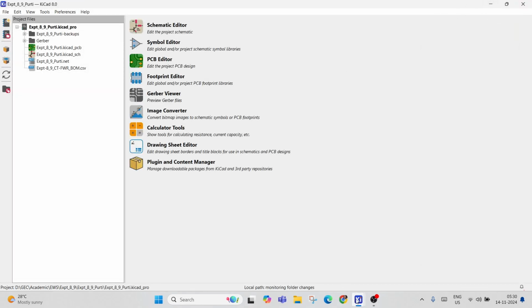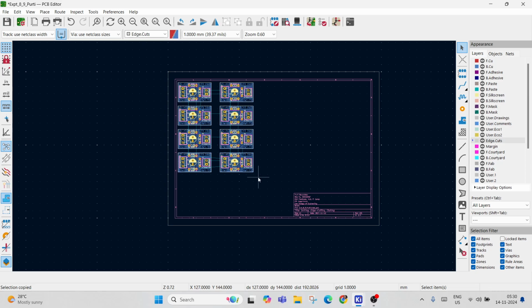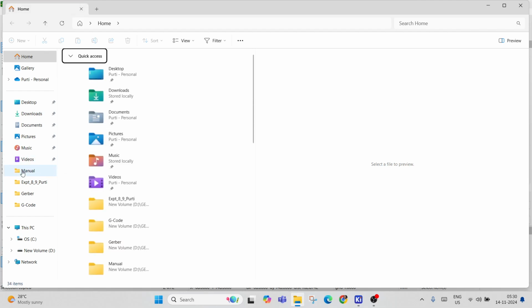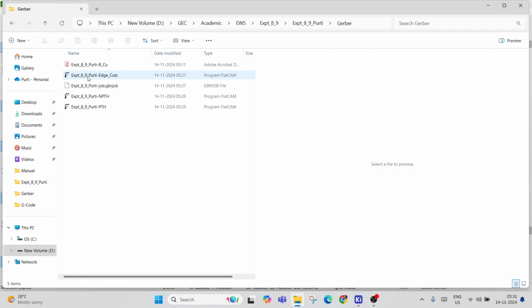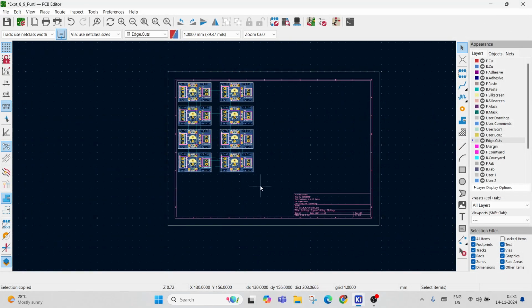Now I was just saying that my PDFs have not got created properly, because the holes for all the pads are exact size. I don't want it to be exact size. Let me see if it is there. This is the one that got created. So holes are not there only. We should be having holes, but they should be small holes. If you see, there are no holes for us to recognize how to match, otherwise it'll become a problem. We have to have holes. So what we will do is, I'm just making sure that, control C, control V.